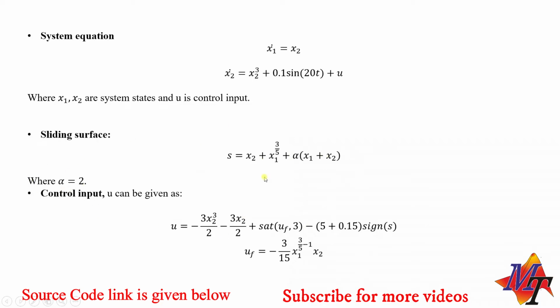Now when we calculate the control input using the invariance condition, which means we differentiate this sliding surface and equate it to 0, we will have some function of u, that is the u equivalent part. This minus 5 minus 0.15 sin s is also included in the u equivalent part, and the 5 sin s is the u d part, that is the discontinuous effort, which makes sure that the system states reach the sliding surface in the initial time, that is minus k sin s.